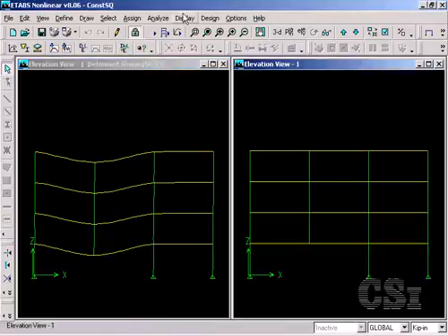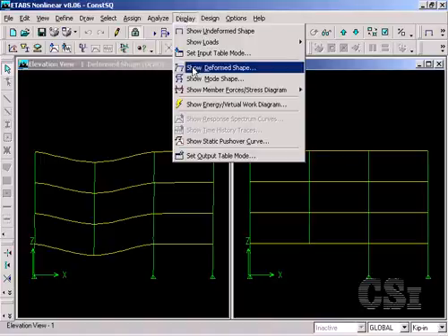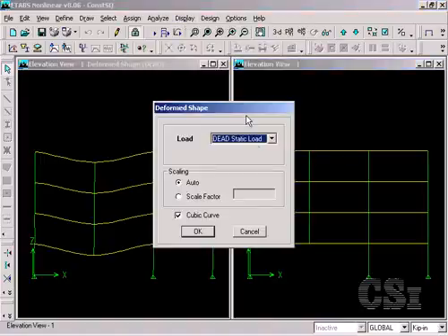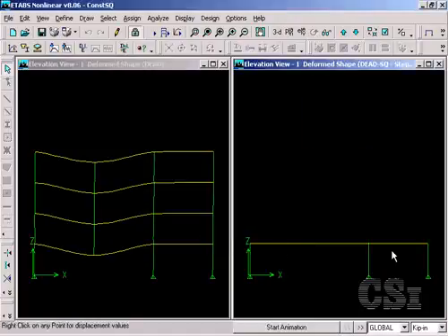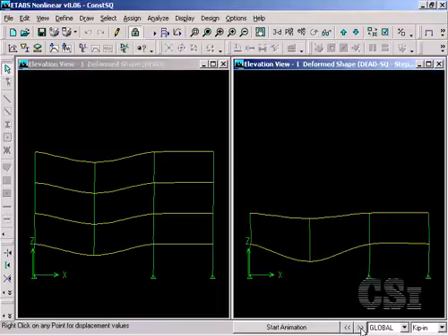In the right window, we will display the deformed shape from the sequential loading to see the effect that this loading approach has on the building. We set the scale factor to 200 to match that on the left. Starting with step 0, the first floor undeformed, we can toggle up the construction stages.